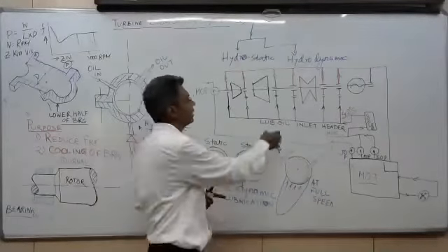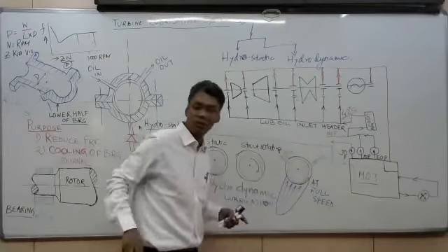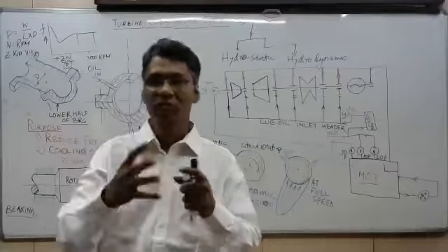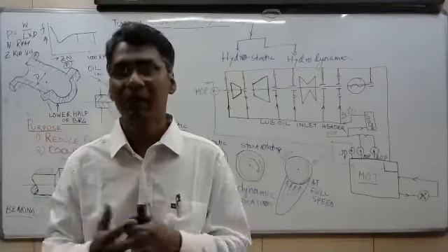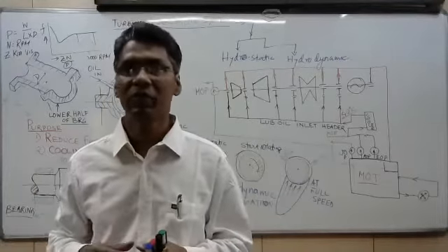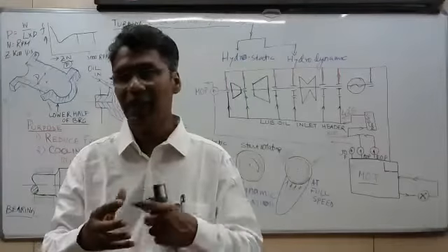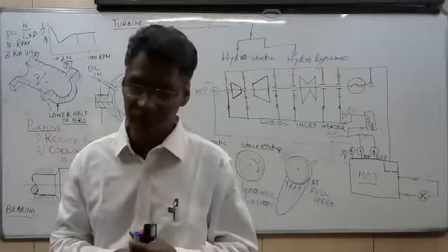We are providing them with pipes and an orifice. An orifice is an item with a flange having a certain size of hole. We can change the orifice as per our requirement. Suppose a larger amount of oil is required, we will give a larger size orifice, and if a lower amount is required, we will give a smaller size orifice.